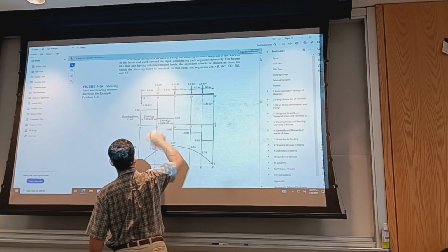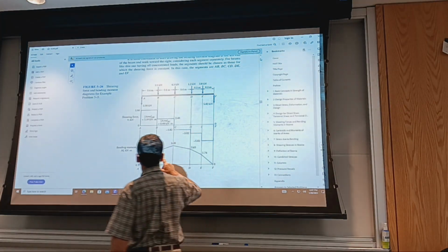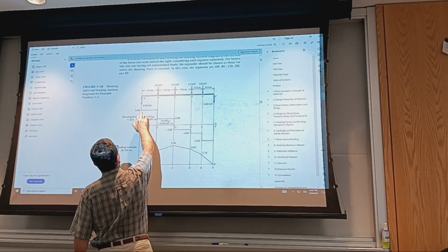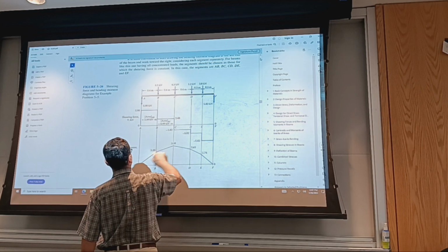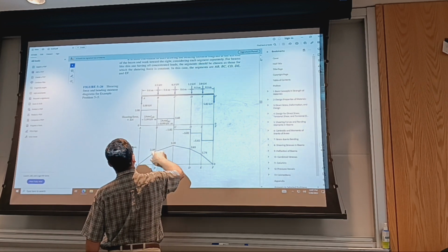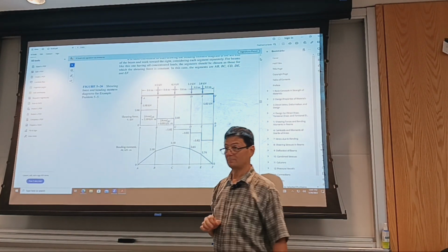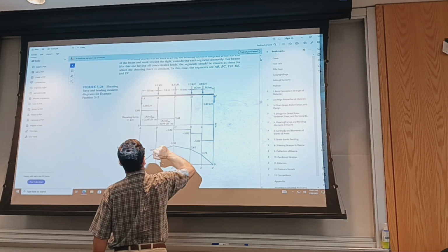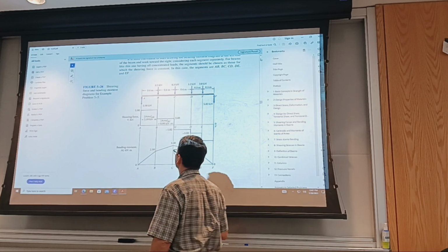Okay, so I started saying that for just concentrated loads, the shear diagram is constant between the loads, and there are abrupt changes on the diagram at the load. On the moment diagram, you're seeing that the slope of the moment diagram in value is the shear diagram, units included. And where the changes occur, we have, of course, cusps.